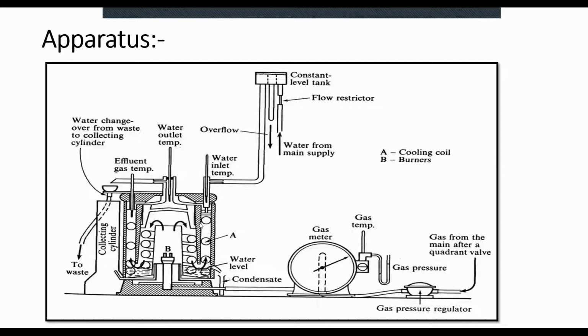The water goes in at room temperature, but after absorbing the heat, the water temperature will be higher than the inlet temperature. If we know the temperature difference between the water inlet and outlet, the density of the water, and the water flow rate, or some volume of water, we can convert that volume into mass of water.